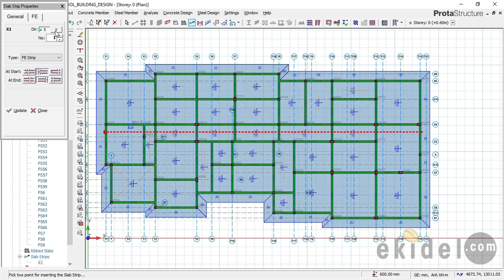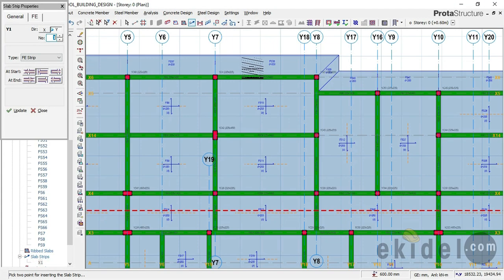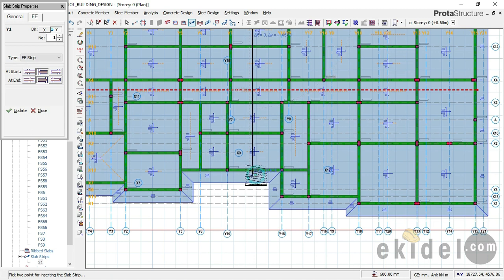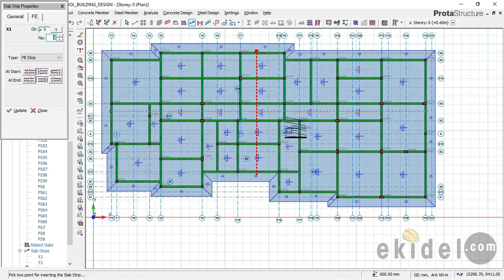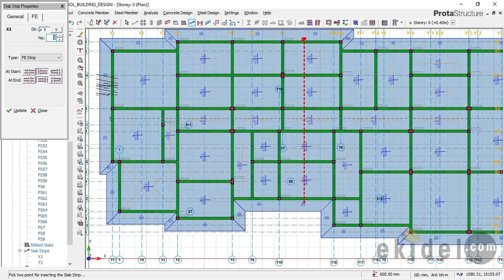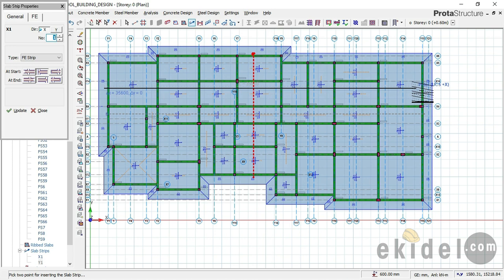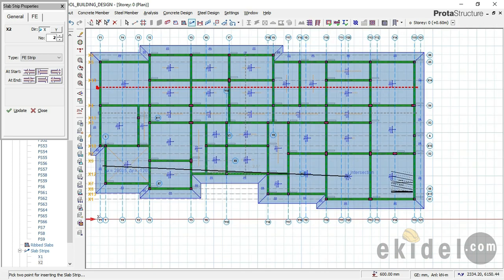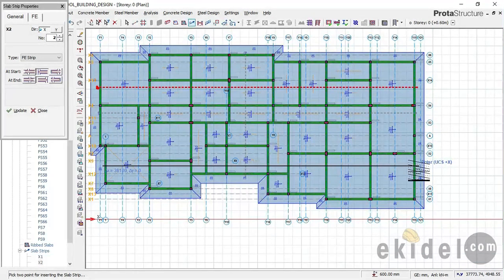Okay, so I'll just go again right now and click on this place here. I'll now cut for the Y direction. I'll do the same thing again. Go here and click up here, and then go over to this very down place here. Hold my control key down, and then click at this very point here. Okay, I can just cut again on X direction and cut this other one. I can cut from here again to this very place here. Okay, for X direction, and then cut also this panel again. The whole idea is just to get my slab reinforcement design reports and also the spacing and the size. Then we will use the Stonebridge detailing template to perform the Raft Foundation detailing.